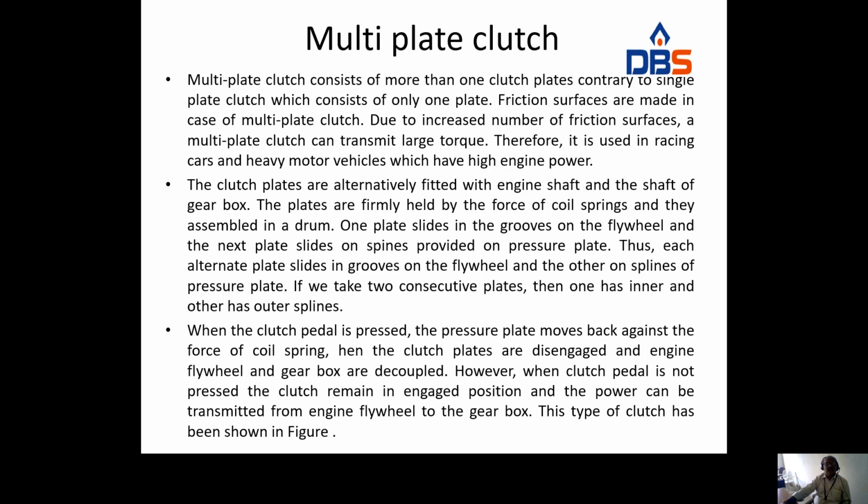The clutch plates are alternately fitted with the engine shaft and the shaft of the gearbox, with pressure plates in between. The plates are firmly held by the force of coil springs and they are assembled in a drum. One plate slides in grooves on the flywheel and the next plate slides on the splines of the pressure plate.